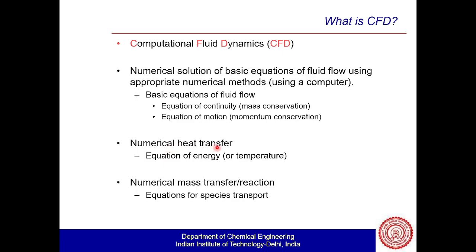If you want to have that heat transfer along with the flow itself, I will entertain your question. Let me finish this slide. For this numerical heat transfer, you have to solve the equation of energy. And for the mass transfer and the reaction itself, you have to solve the species transport alongside the mass and the momentum equation. So yes, you can ask a question, please.